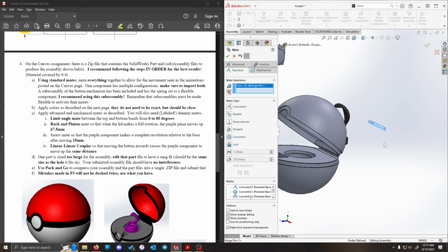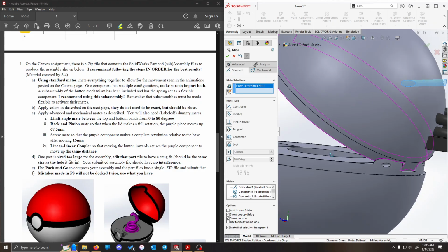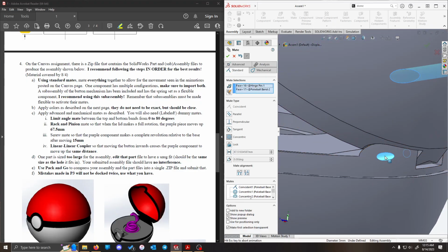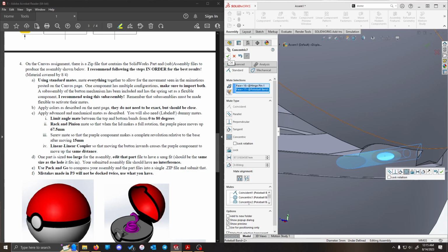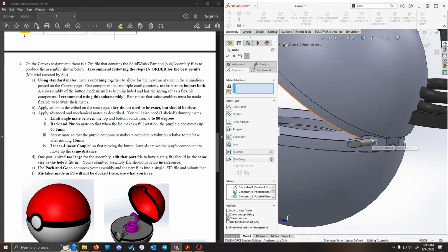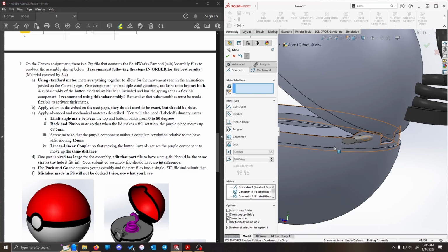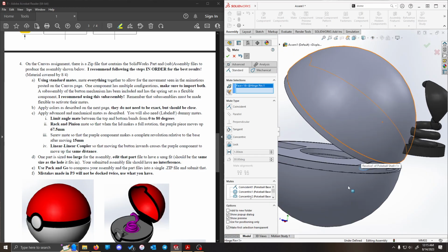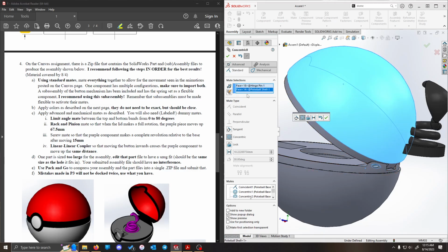So we need the cylindrical surface on the outside of the pin and the cylindrical surface on the inside of the hole. Those are going to be concentric. And to mesh this in nice so that the flat, well, quote unquote flat, the pin stays completely within the hole, it's the same spherical trick. So that end surface is a section of a spherical surface. Oh, oops.